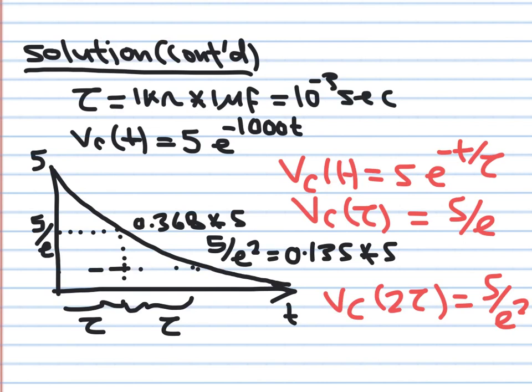So by reducing R and C, we can make tau smaller. By increasing R and C, we can make tau bigger. So tau is our time constant, and whenever in this course we refer to time constant when you have a capacitor, we mean really RC, the product RC.